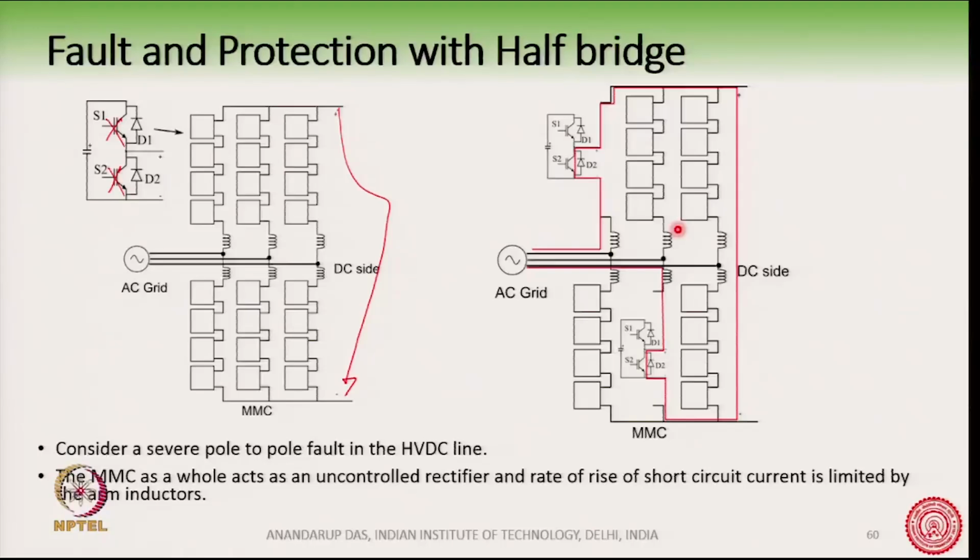But anyway, what I want to say here is that the rate of rise of the current will be limited by the arm inductors, and that is how we should be choosing the inductance, so that under worst condition also the current is limited.